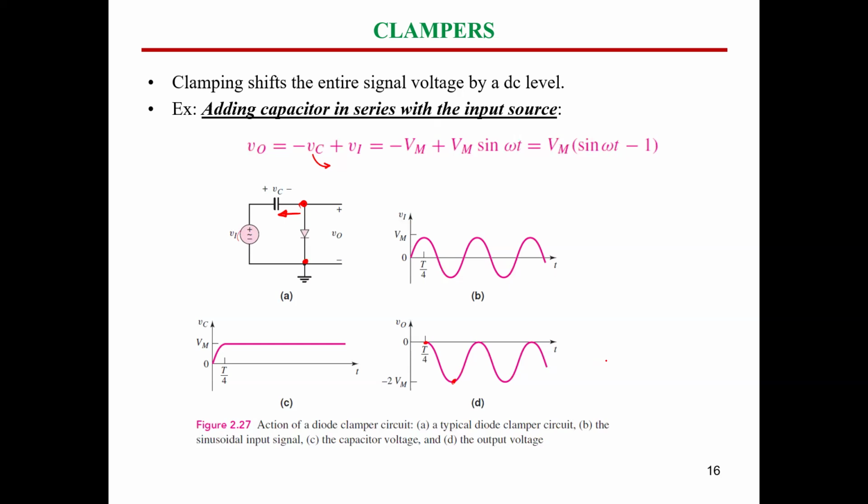So this means now, if we add the diode this way, the output voltage here, guys, is going to be added to an offset, or DC level. So this is the meaning of a clamper circuit here. It makes clamping, or adds a DC level to the sinusoidal supply.